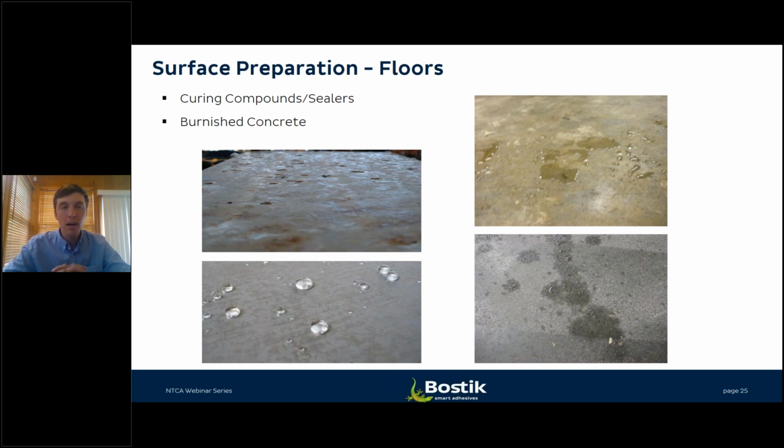In the picture that you see on the bottom left, you can also see a concrete substrate that has beads of water that have been dribbled onto the surface and are not soaking in. That's the same image that you see in the top right of this picture. You can't have a substrate that has no absorption to it and have a good bond, in most cases at least. Now the picture on the bottom right also has the water drop test that actually allows the water to soak into the surface, deeply penetrate the cement, in this case with the concrete substrate, and be a representation that you are ready for a bond.